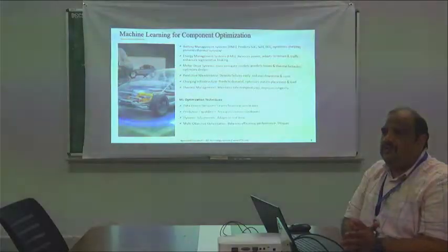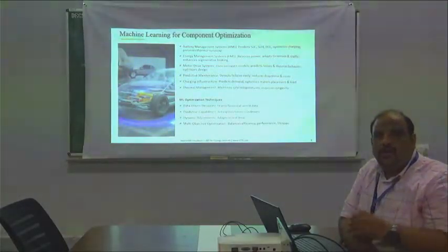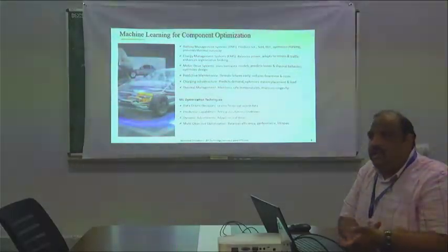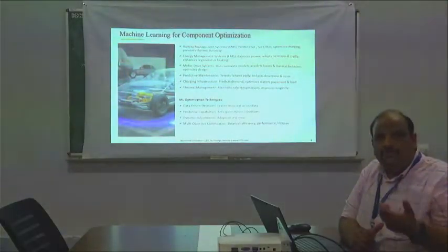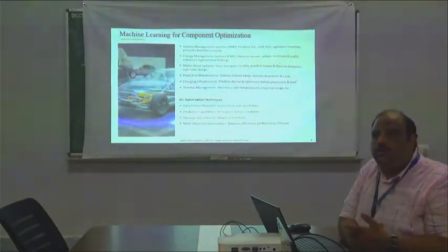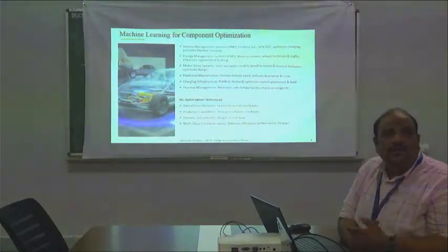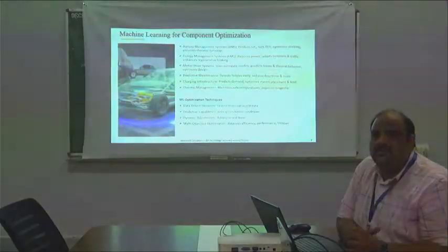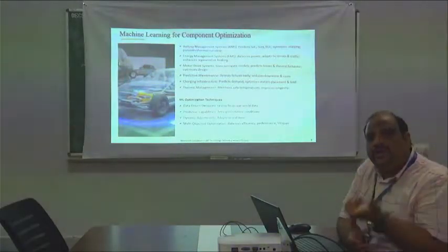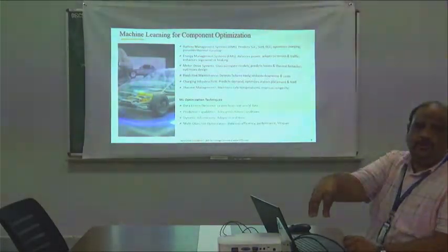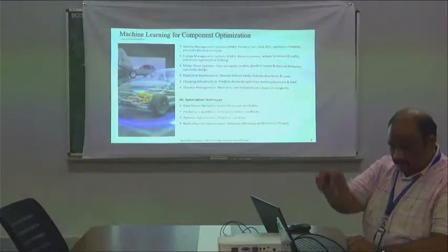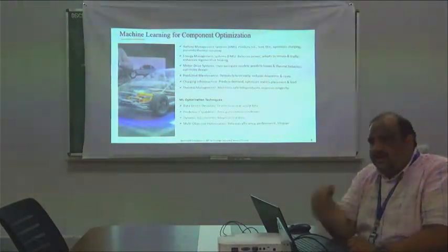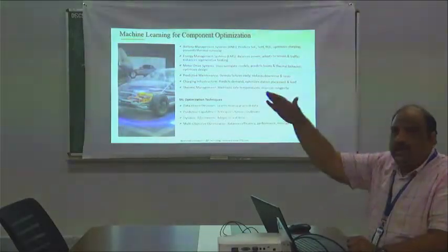So one efficiency we are getting is in your battery cycles: you are not going into deep charging and deep discharging. Even when you are discharging, below 20% a battery safe mode will be activated automatically. How is it monitoring? It is monitoring the SOH and SOC of the battery, and it has to go to the safe mode. And after certain cycles, your battery health decreases.